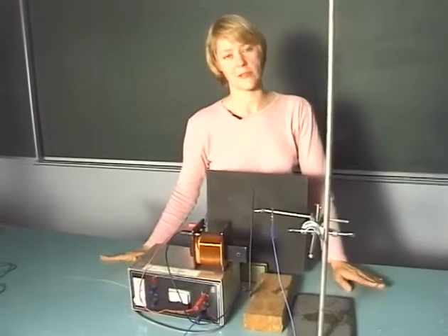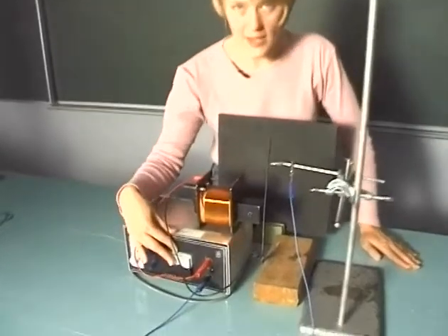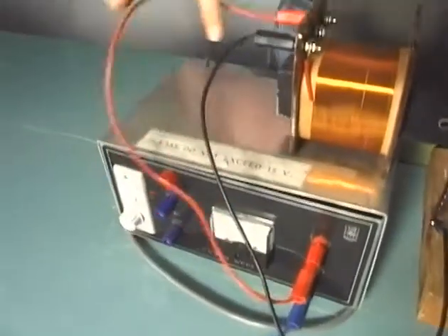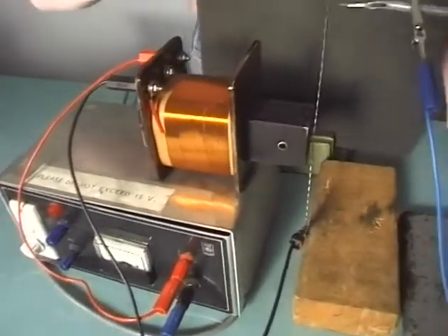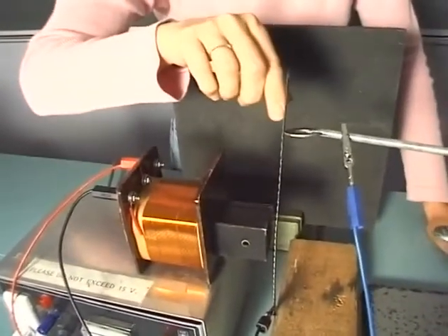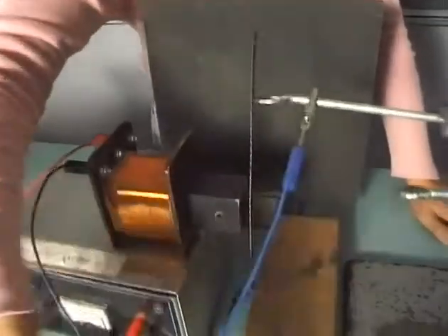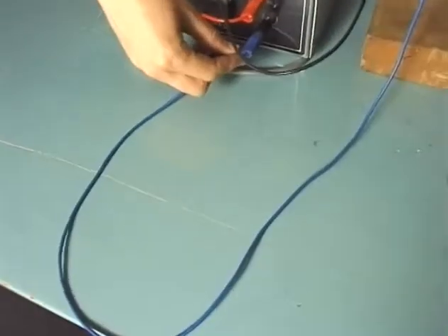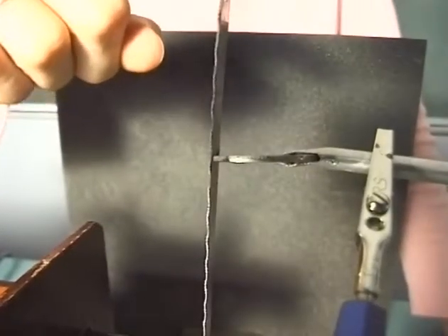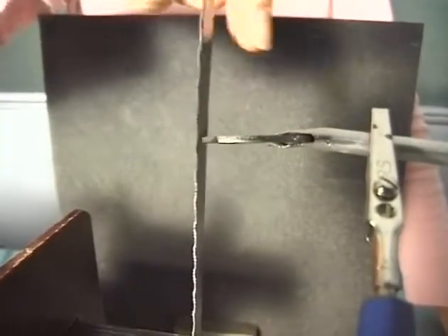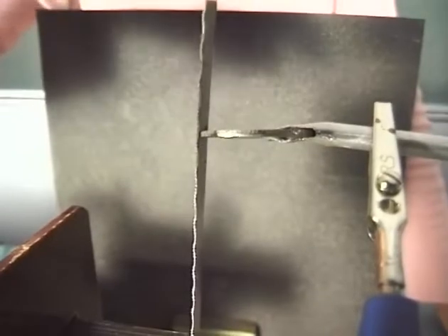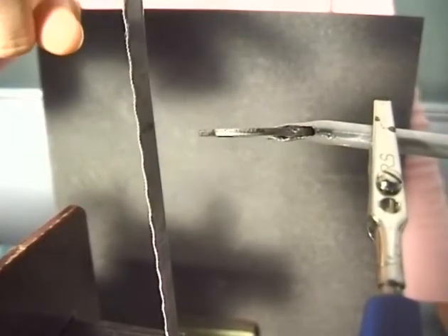Okay, let's look at this device and its circuit. We've got an EMF power source that connects to a coil, that then connects to this saw blade, and then this contact when the saw blade joins it, which connects back to the EMF power source. This saw blade is actually springing in and acts like a switch for this circuit. When it's closed, then the circuit is complete and current will flow. When it's open, then current won't flow.